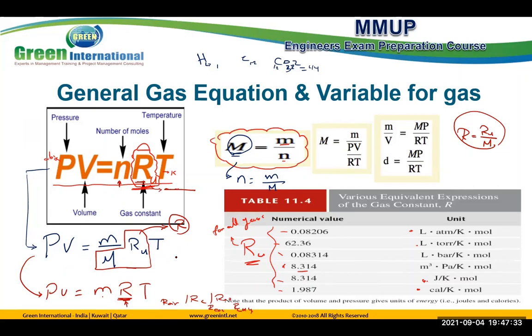Okay, continuing, I think we used this relation in the last exam we solved together. One of the problems used it. PV equal mRT. When you take the volume to the other side, what do we find? This is mass divided by volume. What does mass by volume refer to? Mass by volume means density, rho.